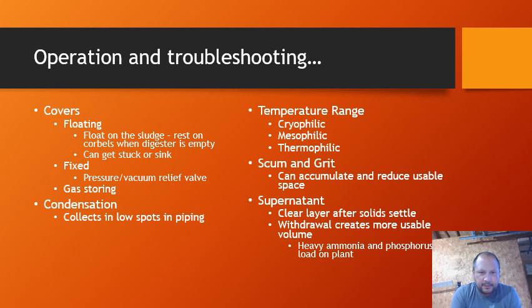If the roof of your digester lid should happen to leak and rainwater is allowed to build up in that annular space, it can reduce the buoyancy of your digester lid to the extent that it actually will sink into the sludge.